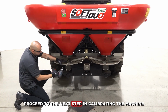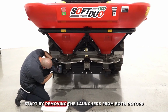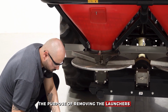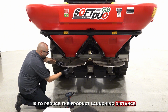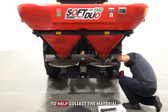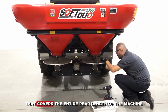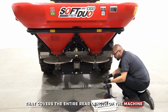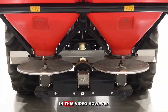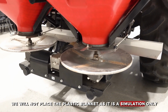proceed to the next step in calibrating the machine according to the new product. Start by removing the launchers from both rotors. The purpose of removing the launchers is to reduce the product launching distance, making easier the material collection. To help collect the material, place a plastic blanket underneath the rotors that covers the entire rear length of the machine in order to collect all the material without loss. In this video, however, we will not place the plastic blanket, as it is a simulation only.